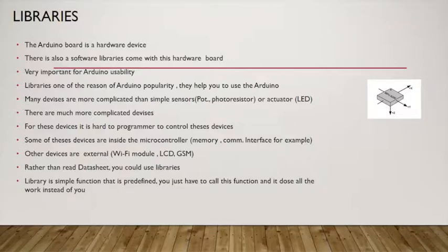It needs to be calibrated every time before you use it. The user shouldn't have to worry about the calibration every time he wants to use the device. So as a programmer, when you design the device, you should calibrate the device and save the calibration data into the EEPROM of your device.